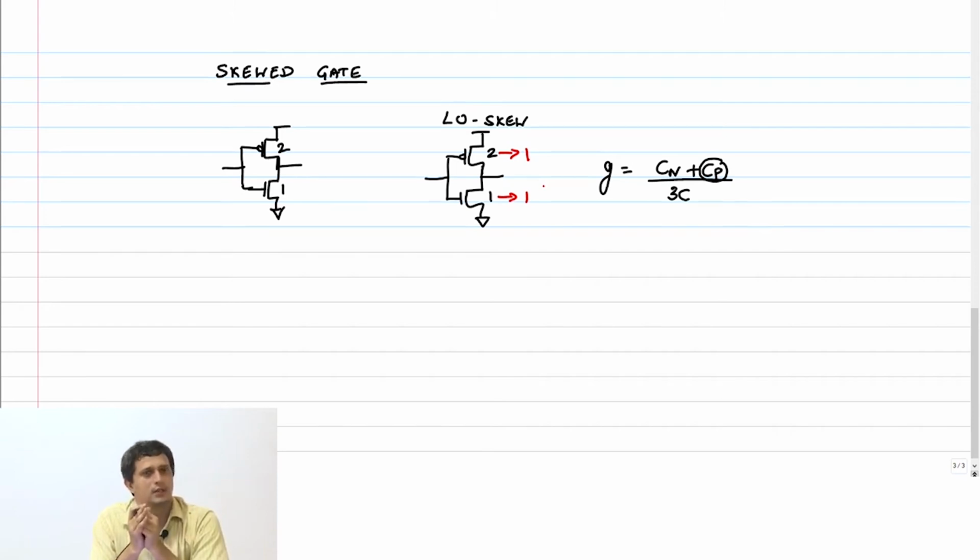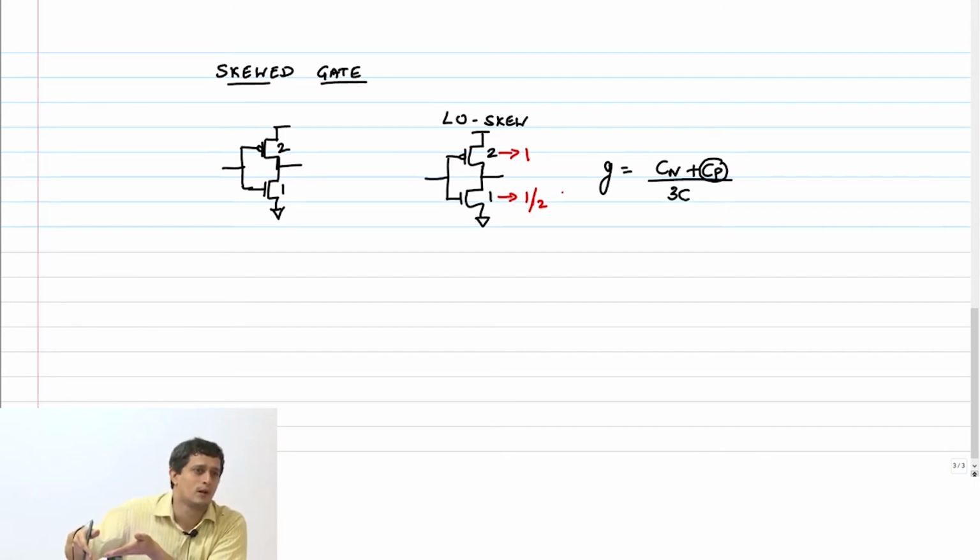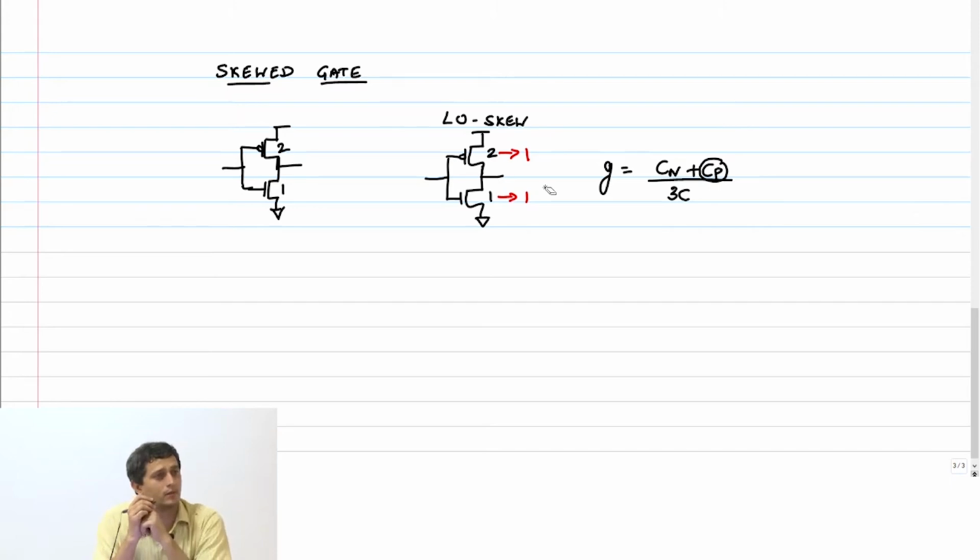Here what I have done is, since the falling edge is important, I am not changing that resistance. That is already R. I cannot increase that resistance now by making that smaller. So the other option is, of course, if I make this, let's say, half, you might think that the capacitance will drop, but then my resistance is increasing. You can only do this resistance increasing if another transistor on the stack is able to compensate for that. Clear? Therefore, I cannot make this half. I need to keep it as 1. But the top guy, PMOS transistor, I can make it as 1.